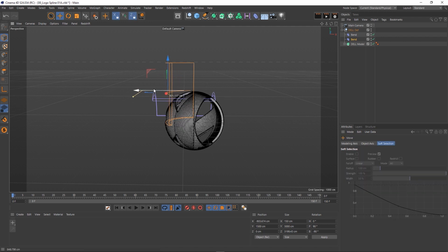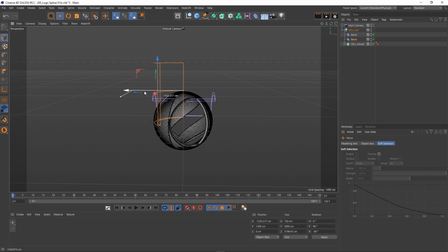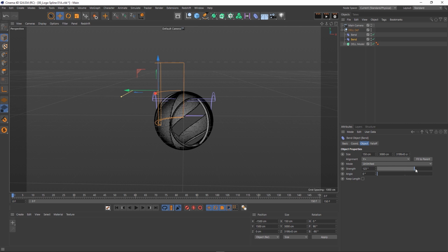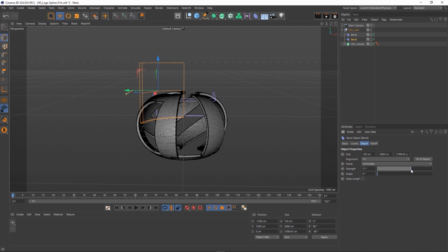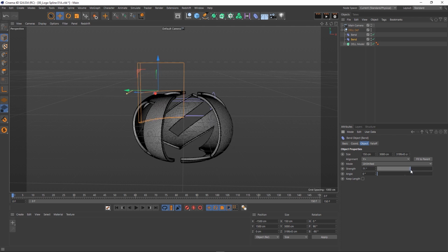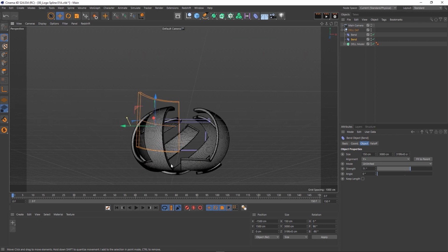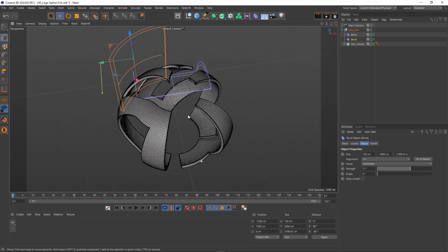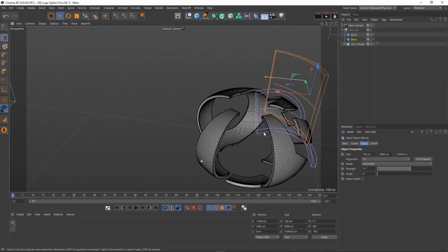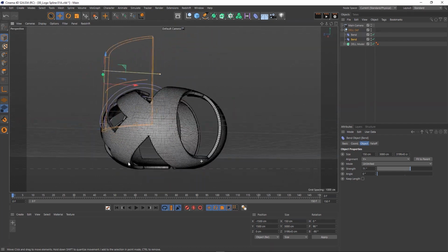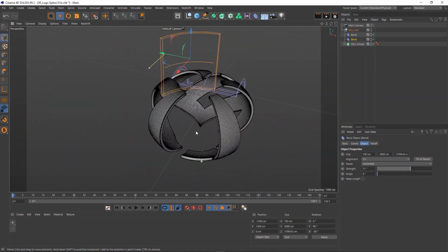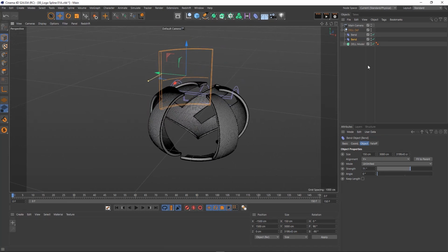I'm just going to move it to the left. You can see what's going on here. I need to bring it right in the middle. So Y, selected, 3000, go to the Y, make it half, minus 1500. Excellent. And then just relax it a bit so we avoid any overlaps. And I think this is what I'm looking for at this point. And there you have it. We have this nice deformed logo that looks like, I don't know, a sphere or an orange peel.